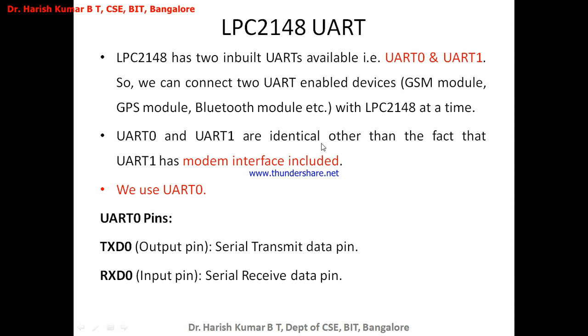Except that UART 1 also has a modem interface included, but you don't find a modem interface in UART 0. So we have 2 built-in UARTs available in LPC 2148, UART 0 and UART 1, and they are identical. One additional thing that you find in UART 1 is an interface for the modem. That means you can also connect a modem to it.